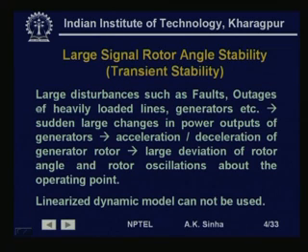What happens when these take place is sudden large changes in power outputs of the generators, because if a transmission line is tripped or a short circuit occurs, the generator outputs change considerably, and this change in generator electrical output causes an imbalance between the mechanical input to the turbine generator system and the electrical output of the generator, causing acceleration or deceleration of the generator rotor.